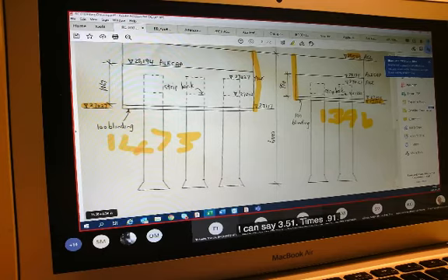My dimensions, I can do this in one of 2 ways. I can say 3.51 times 0.91 times 0.1, and I have 4 of those sections of blinding, but I will still have to deduct the piles that I see protrude through the section where I'll be casting the blinding, and that will be 0.24 by 0.24 by 0.1 times pi times 12.